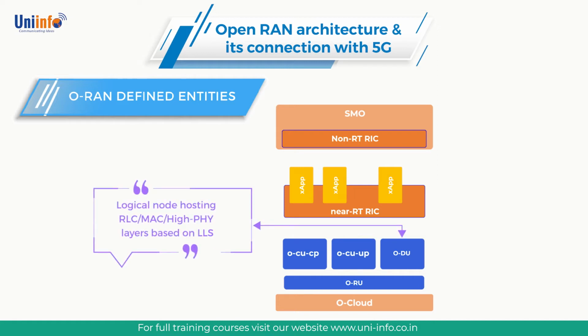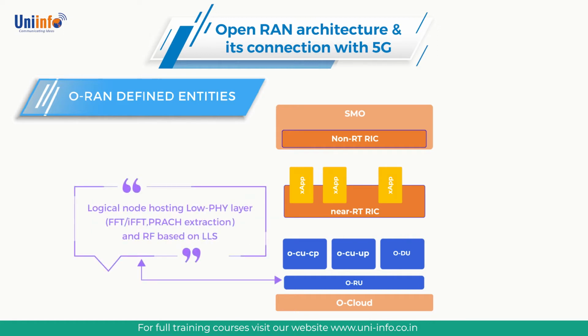Eleventh, logical node hosting RLC, MAC and high physical layer based on LLS. Twelfth, logical node hosting low physical layer, FFT or IFFT, PRACH extraction and RF based on LLS.